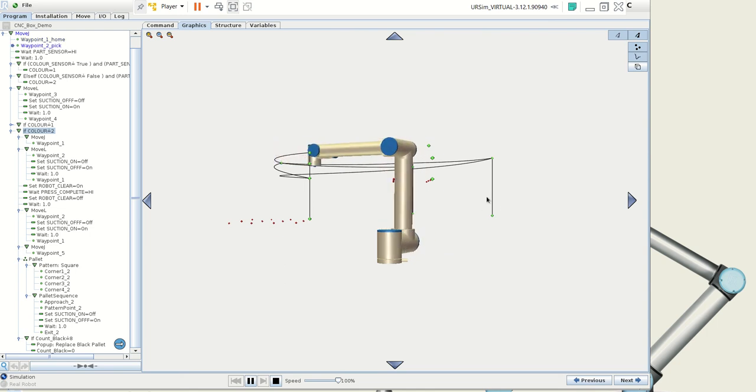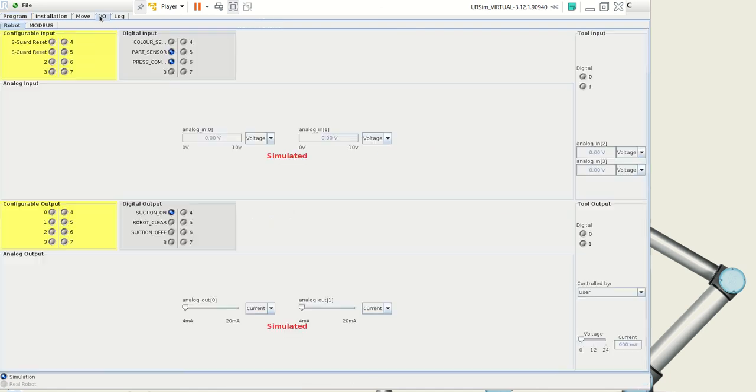That it's just doing that operation before it actually gets palletized at the end. So it's just how we can do a bit of a simulation with the kind of limited resources we have here. All it is just an I/O, so you have an input because the output of the other machine is going to send that across, so the robot will receive it as an input, and then again the robot, to let it know it's clear, sends the output across, so the PLC will receive that as an input signal, and then they can kind of communicate between each other.